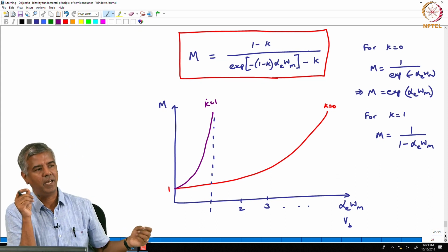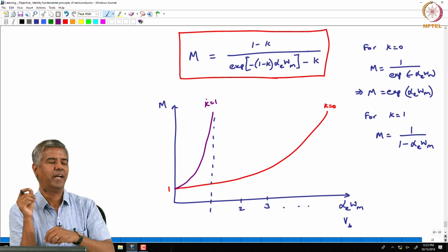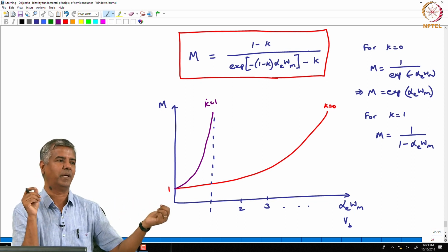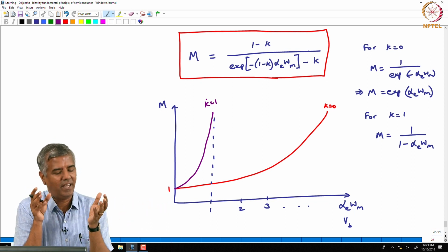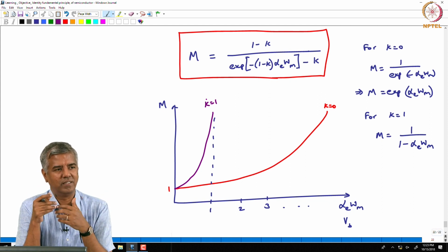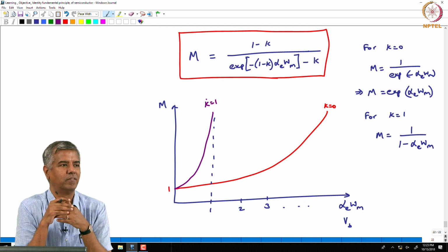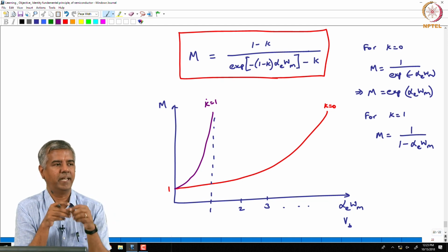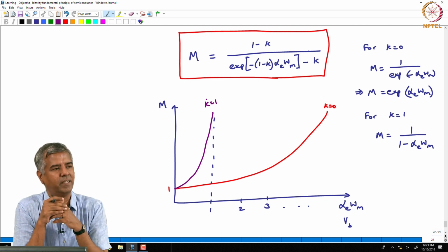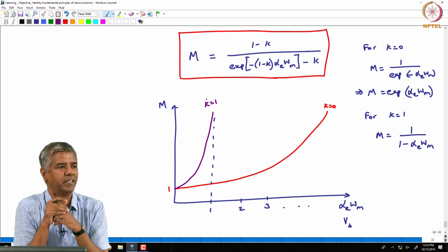So, you are going to have these holes filled by another electron, and in that process you essentially have the holes moving this way. So, although physically you cannot think of this hole generating an avalanche process by itself, the hole does create a perturbation which essentially generates secondary electrons that are left behind, right.